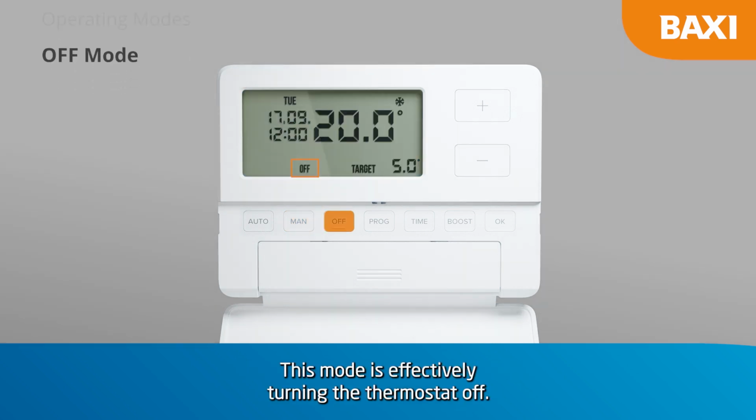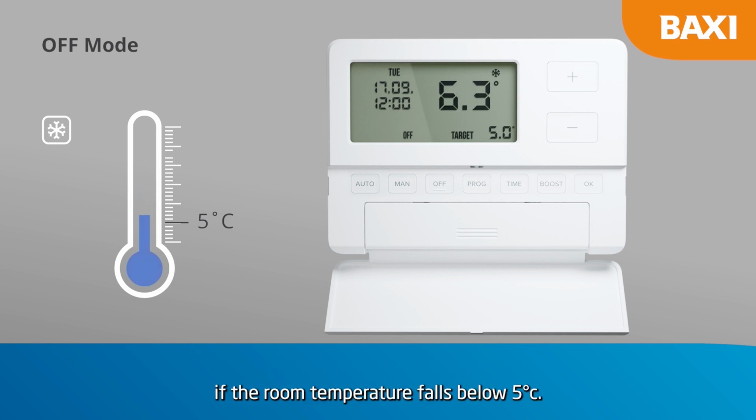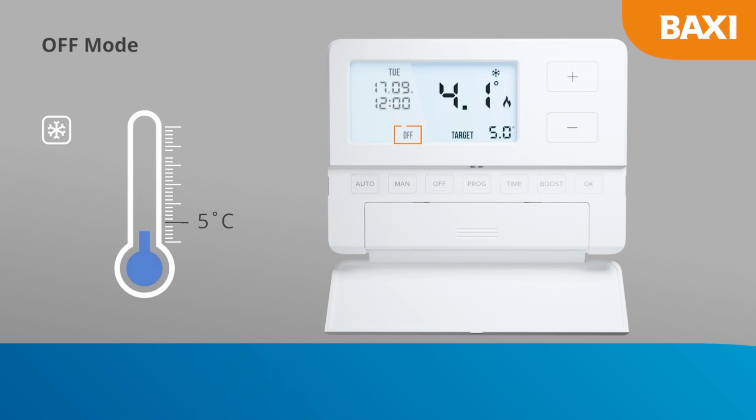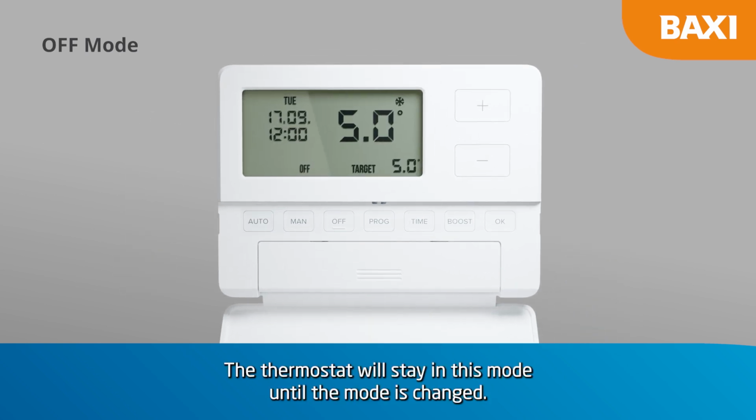Off mode. This mode is effectively turning the thermostat off. Frost protection is active in this mode, so the thermostat will turn on if the room temperature falls below 5 degrees Celsius. Off will be displayed on the bottom of the screen. The thermostat will stay in this mode until the mode is changed.